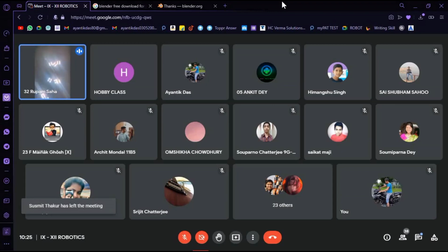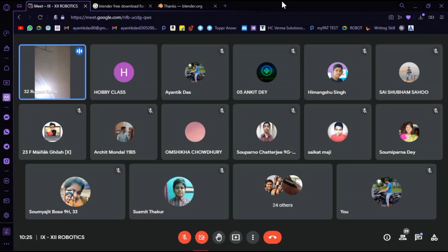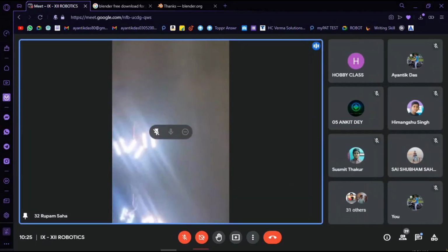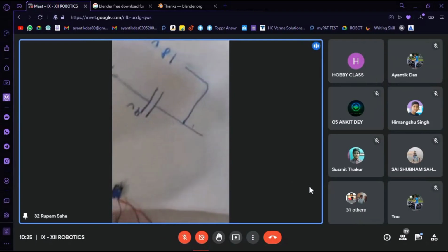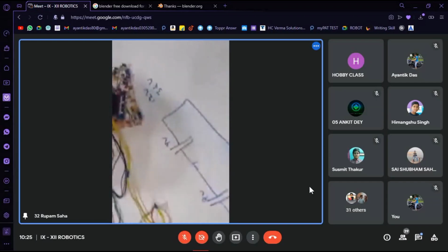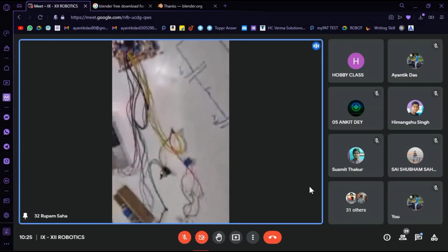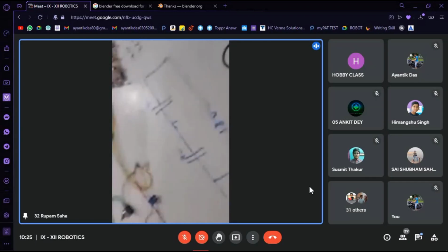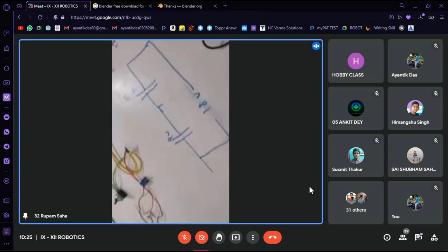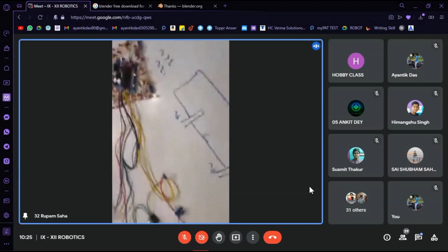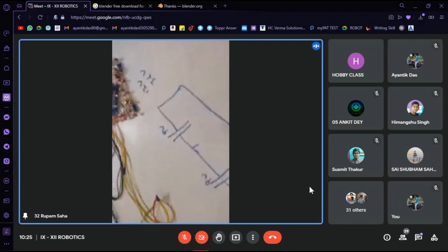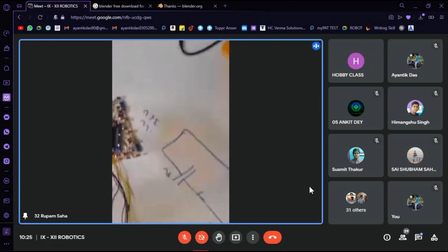Now this is the LED, which is actually 54 watts running right now. And I can simultaneously run a big drilling machine motor just with the help of a 12 volt battery, which is not possible otherwise. If I directly connect the 12 volt battery, all of the circuit just stops working, because 12 volts isn't enough to run all of this simultaneously. So if I use my circuit in this place, it can step up the input voltage, and thus I can run a heavier or higher voltage device just with a lower power source.